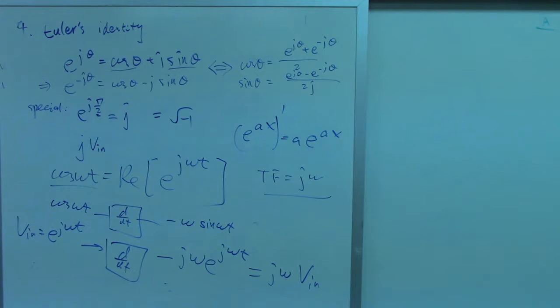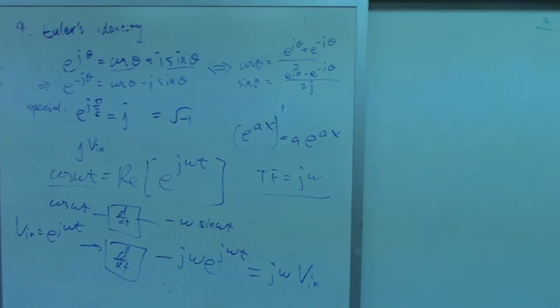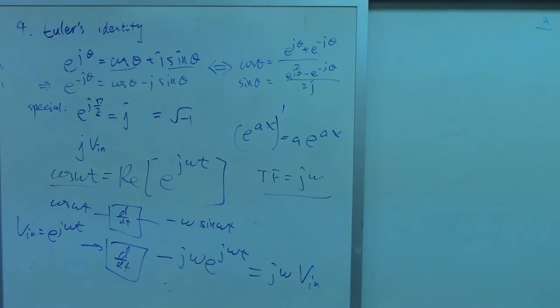So this transfer function idea is very important. No matter if you discuss circuit analysis, control systems, a lot of things, the transfer function is always the output divided by the input. For example, for a linear amplifier, the gain equals 100 or equals 20 dB. So we know output over the input. And that is special because the frequencies are the same. So 100 cosine omega t over cosine omega t equals 100. That is, the gain is constant. But in general, that is called the transfer function.